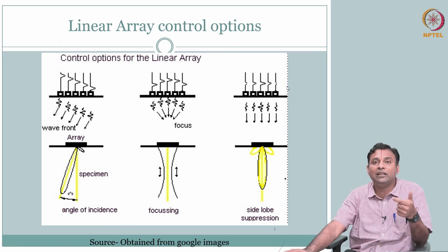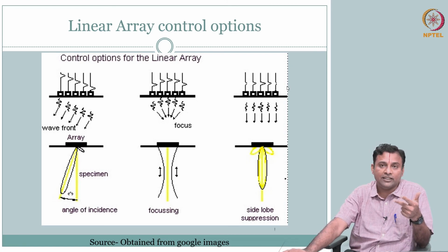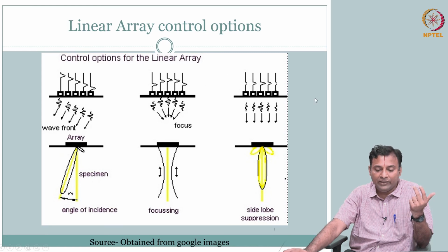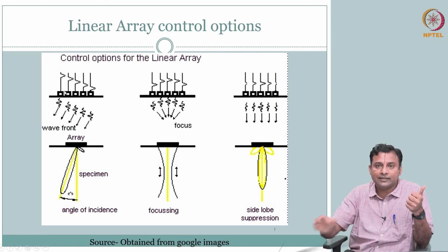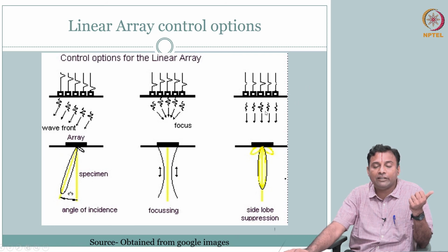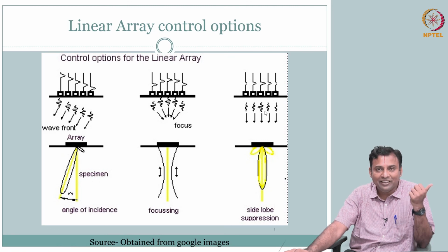So, all the major limitations that we talked about with respect to mechanical scanning: with the array, having control of each of the crystals separately gives us the flexibility to overcome them. Whichever direction I want I can scan, however I want to focus I can focus, whichever apodization I want to apply I can apply. Pretty neat, right? So let's jump in and see how to execute this.